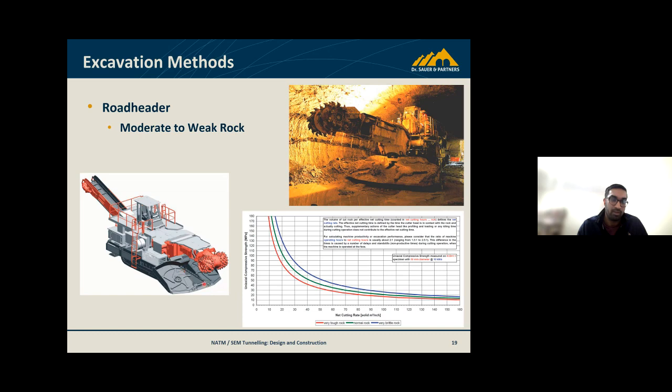The spoil is lifted up through the middle of the machine and constantly deposited into a dumper truck or whatever is waiting there to be loaded and taken away straight away, and you just have that turning around constantly and get a pretty good advance rate going. And usually that's what it boils down to: advance rate equals money, and a lot of that analysis has been done.